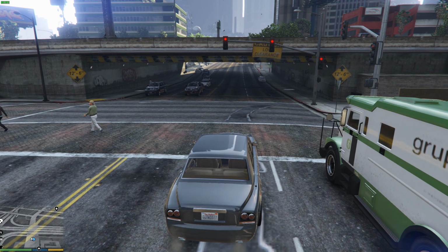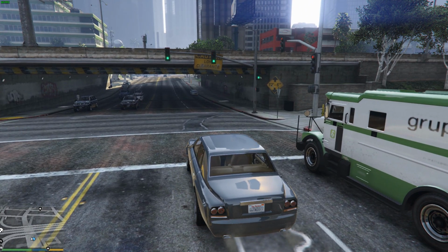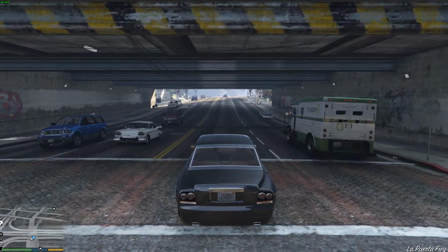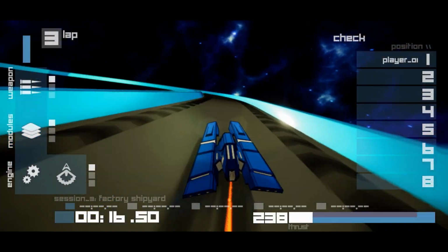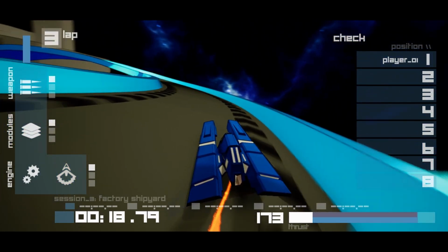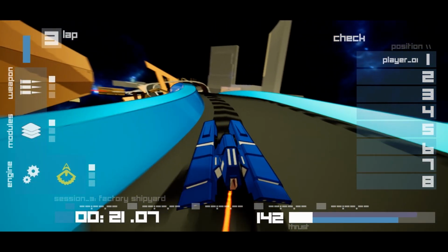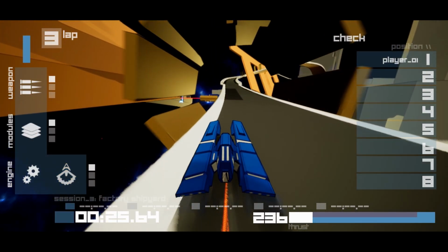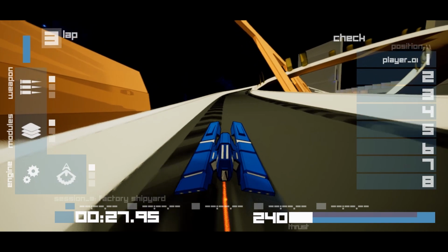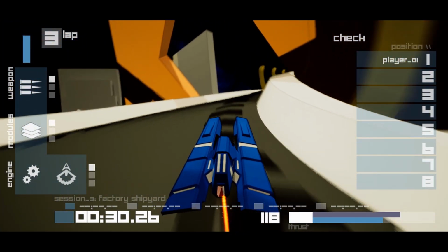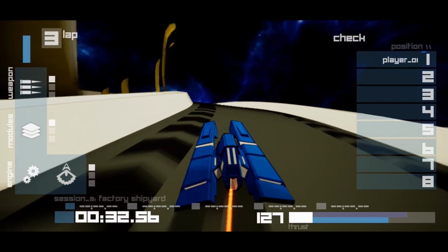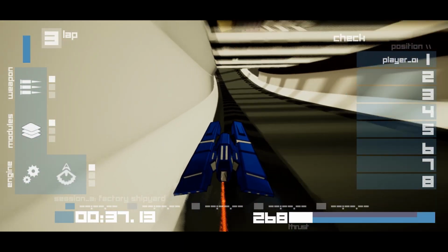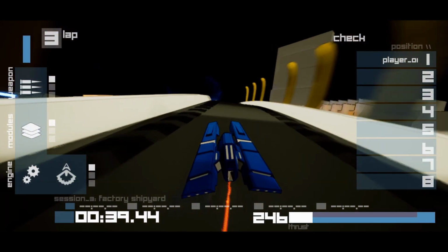The principle here is adding simple layers at each stage of the sound design so that the end product sounds more complex and nuanced. The main driver will be the crossfade by param node in the sound cue. We'll create 3 versions of the same cue, adding an extra layer at each stage. We'll round that off by creating a tremolo effect in the vehicle blueprint. This will provide an extra layer to the sound and show you how you can start blending different sounds together to get a richer and more detailed engine sound.